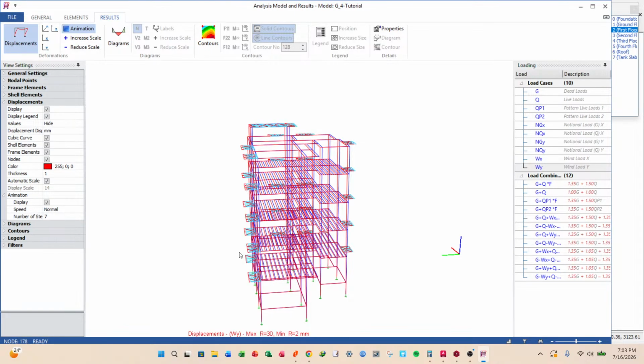So we shall reorient our columns and position them in the best way possible, both with respect to the moments and also the architecture space. So we shall be weighing between architecture space and structural capacity of the columns.